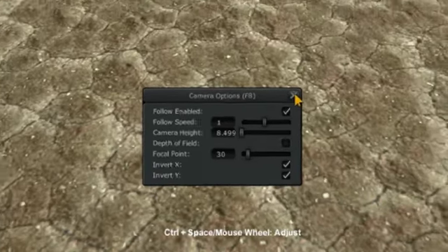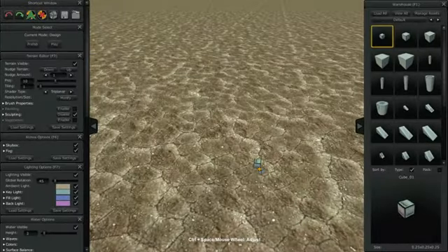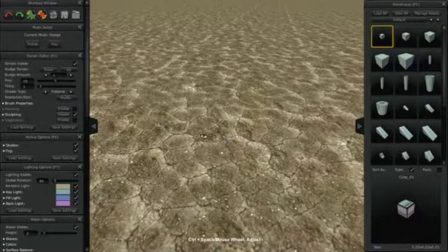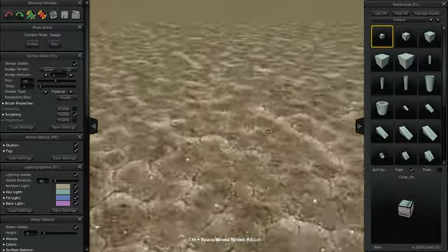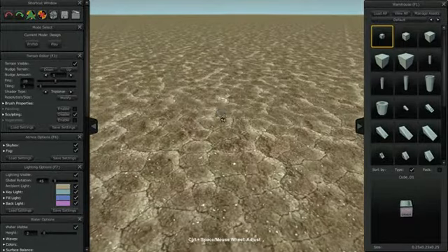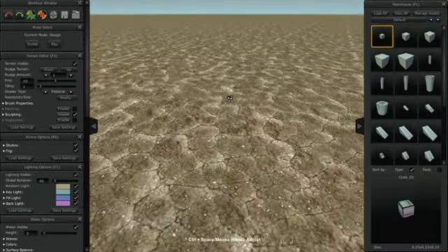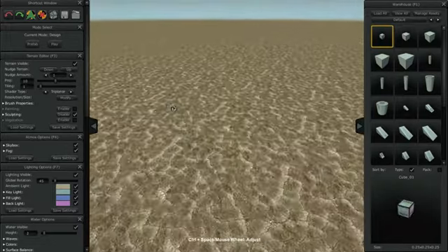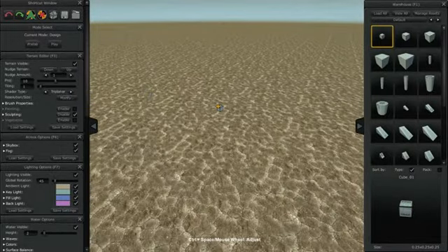You can also rotate, translate, and move the camera by pressing down the Alt key on your keyboard in combination with the clicking and dragging of the left, right, or middle mouse buttons. Rolling the middle mouse button or wheel will also zoom the camera. Alt, left mouse button, click and drag to rotate. Alt, middle mouse button, click and drag to move. Alt, middle mouse button, roll to zoom. Alt, right mouse button, click and drag to zoom. If you are using a Mac, AGF uses the multi-touch gestures you can set up in your mouse settings.